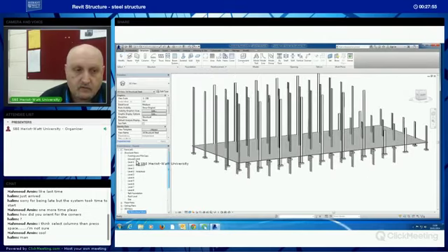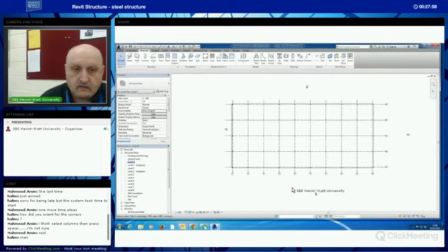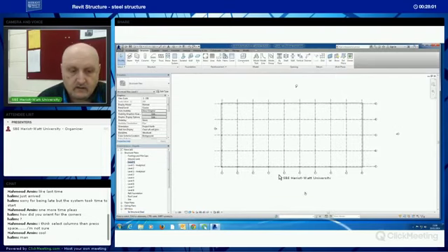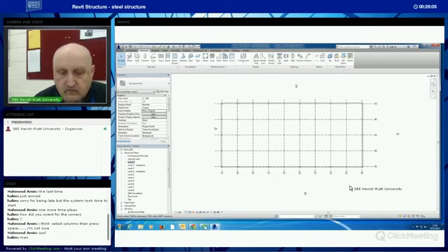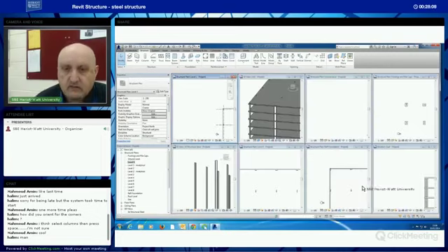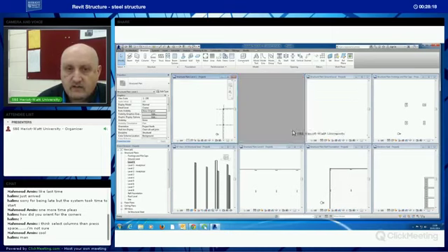And then I'm going to go to the level 1, I think, and I'll put the grids in. Now, if I WT, that's a new short keyboard shortcut for you. WT will show me all the windows I've opened in this project. Now, this one I want to keep. I don't want to be seeing the default 3D view, so I'll just close it.